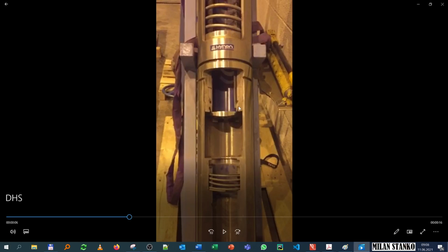Okay, and this part you will see now what moves. What moves is this. You see here a piece of pipe inside the valve, which is pushing the flapper. When this one is extended, it's going to be pushing the flapper against the wall, and then the valve is going to be open. And what is trying to keep it closed is this spring. So when there is no hydraulic force, here is the hydraulic piston that I was using to put force and to counteract the spring.